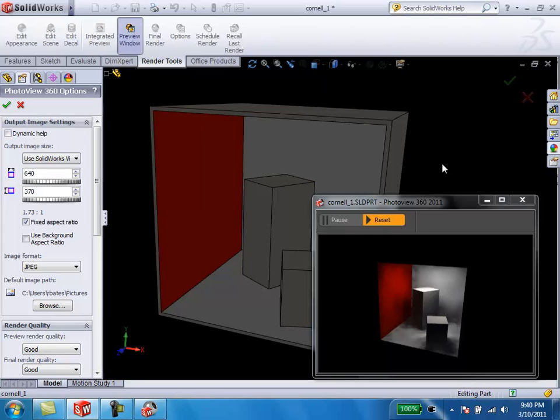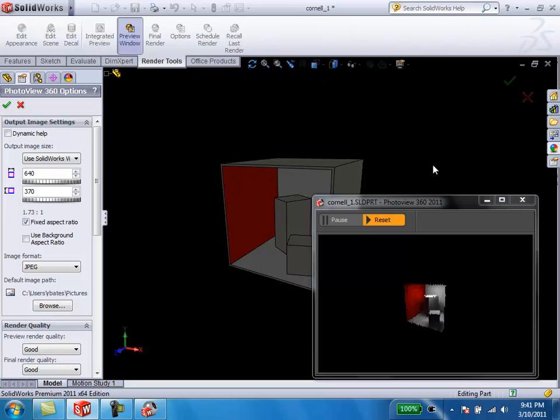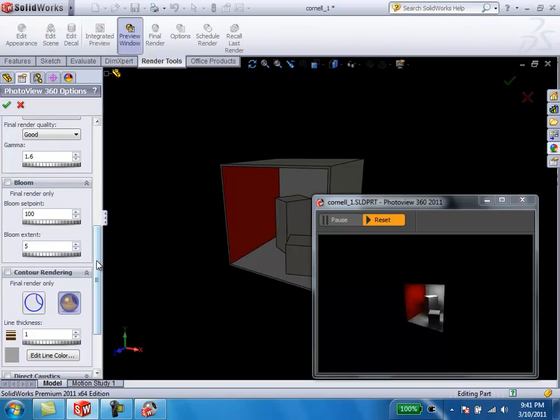It's an interior type scene, not what I would call a tabletop object, something that's just sitting out in the open with an environment around it providing you lighting. When it's an interior type scene, the light needs to bounce off of everything a lot more to produce a final result that looks good and not noisy. And that's when you really need to go up to maximum.